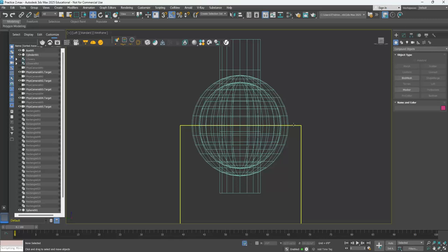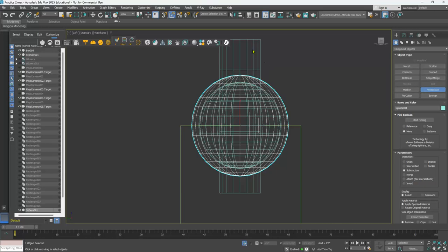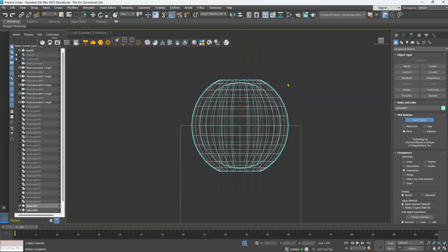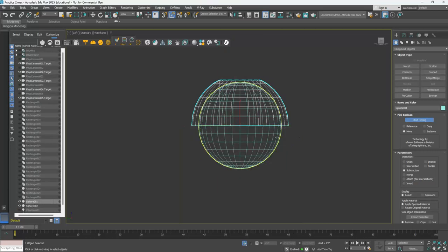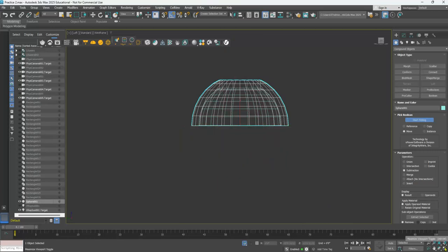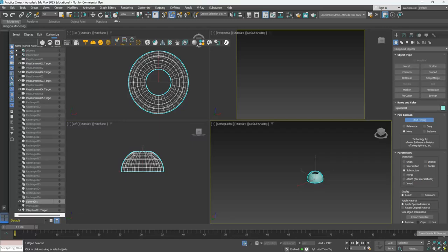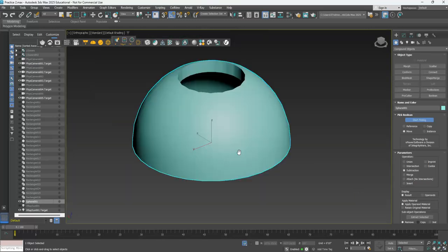You pick whatever, yeah, go ahead. Yes, the one you're gonna keep, right? Yeah, so I'm gonna keep this large sphere. So I'm gonna pick this first, then I go to ProBoolean, right? And I can start just clicking, right? I should be able to go here to subtract, start picking, and I do 1, 2, 3, right? And now we should have this kind of shape like this.